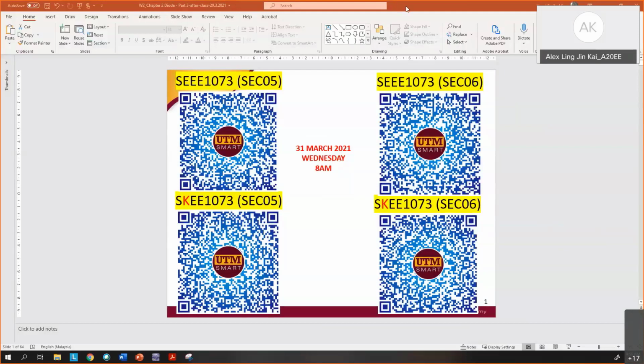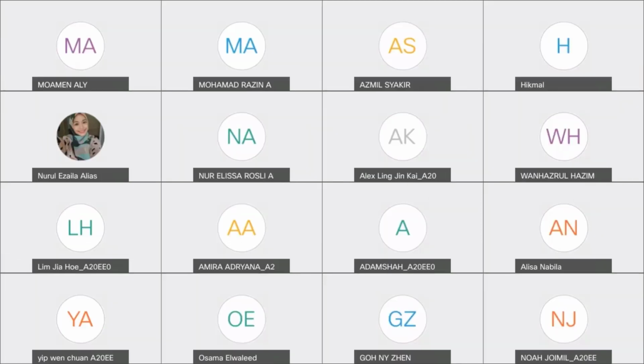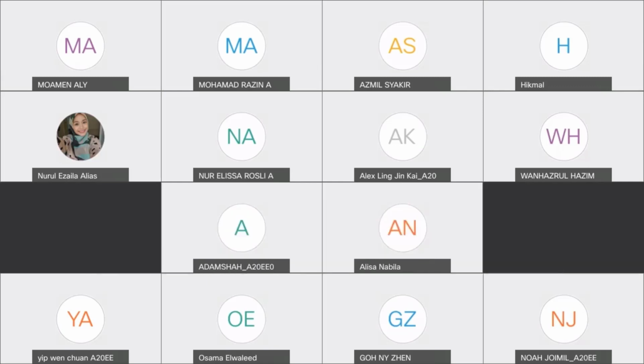About the PIV, how to explain? PIV is the peak inverse voltage. When you have, for example, a positive cycle, there will be a diode forward bias, but there will also be a diode reverse bias, right? That reverse bias diode has a peak inverse voltage, meaning the maximum voltage that could occur during the reverse bias. That is peak inverse voltage. So when you calculate peak inverse voltage, it is actually the voltage across the reverse bias diode.